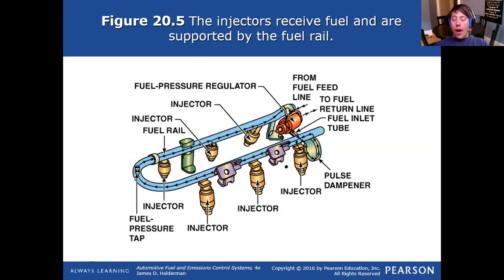They act as a shock absorber, so they can push back to a middle position of travel, and as fuel goes down in pressure, they're able to add a little pressure, and as fuel pressure is too great, as it hammers, it'll absorb that impact. It literally acts just like a shock absorber on your vehicle's suspension. It dampens those violent shocks and smooths everything out.